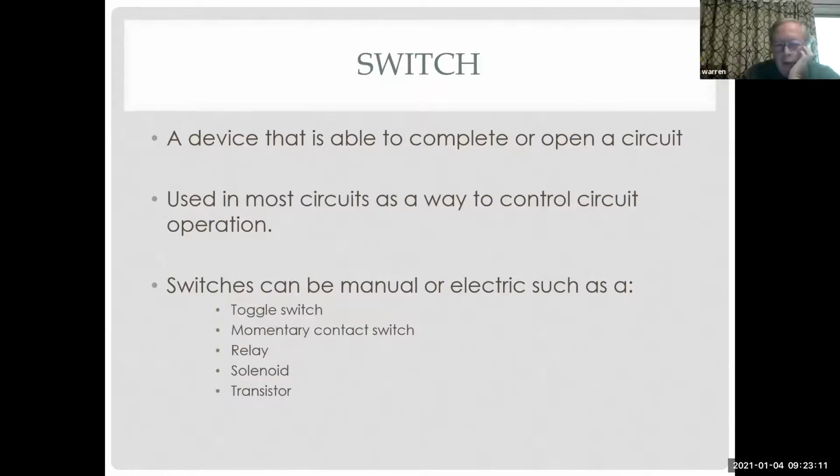I got one quick question to make sure I understand the short. Let's assume you test a switch and current is flowing open or closed. I would call that a short circuit. Yeah, it's a shorted switch, not a short circuit, because you're still flowing through the ground and you're still flowing through the load and not blowing the fuse. So the circuit's not shorted because the light's on all the time. Right. The switch is shorted because you can't open it. Thank you, sir. Makes sense.